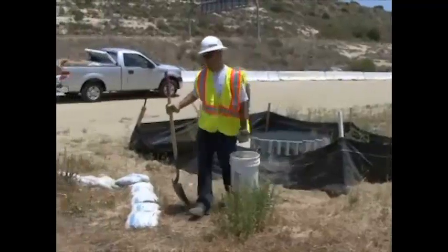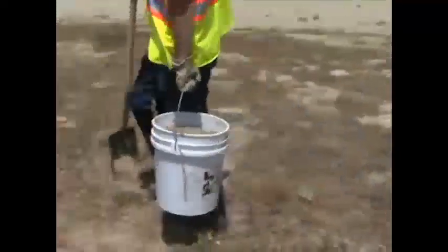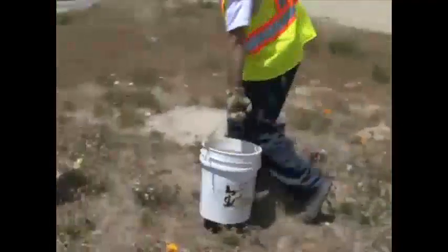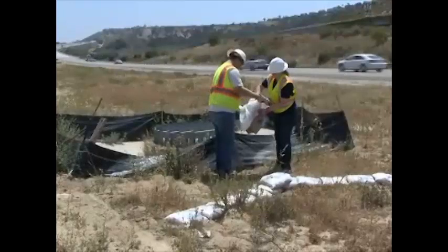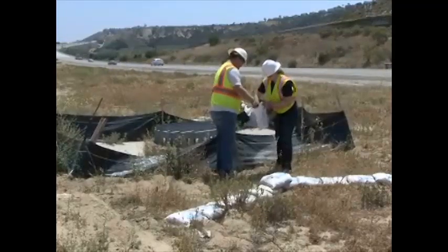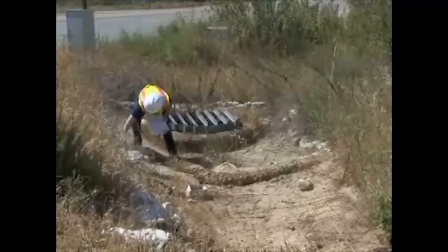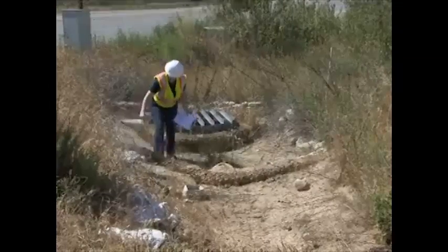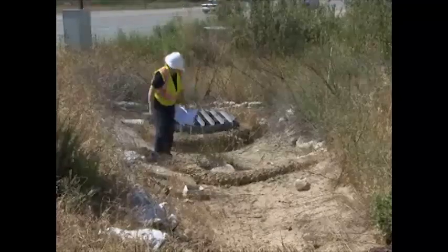Deposit the removed sediment within the project limits so that the sediment is not subject to erosion by wind or by water. Remove and dispose of trash and debris in accordance with the project special provisions. At locations where rills and other evidence of concentrated runoff have occurred beneath the drainage inlet protection, the protection shall be adjusted to prevent another occurrence.